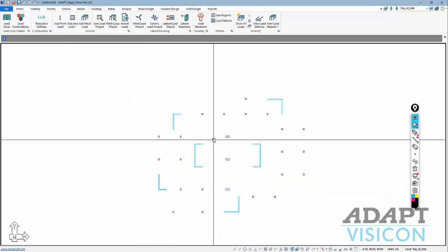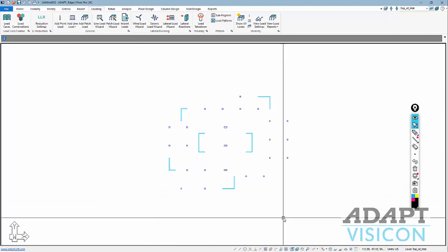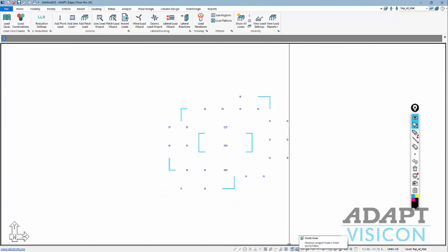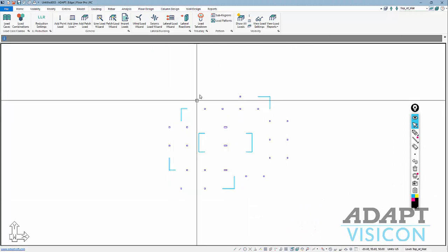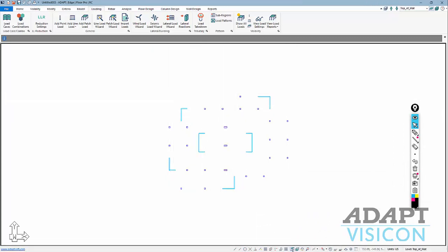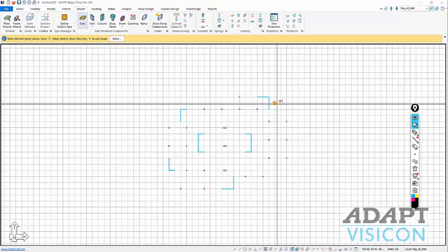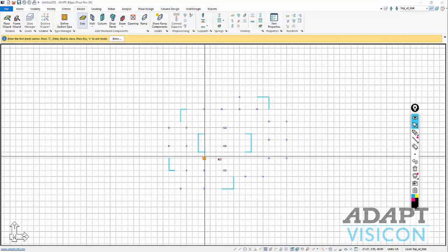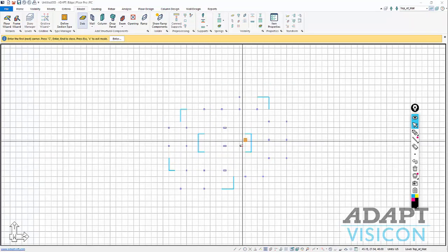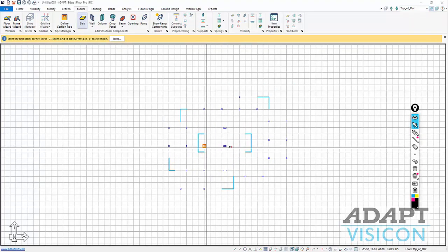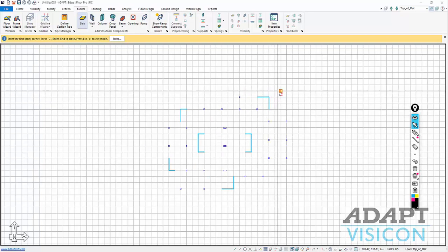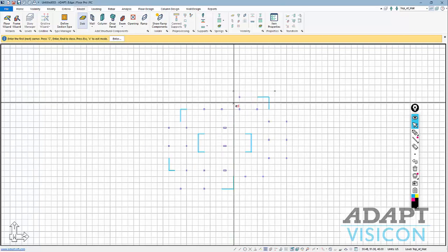And here we want to develop the foundation slab that we're going to use for modeling really the pile caps and the piles. We're actually going to represent it as a mat with piles. So I'll turn back on my grid, and I'm just going to build some mat slab, and I'll have thickenings for the core walls and some of these perimeter walls. So we'll go ahead and I'll just draw a mat.